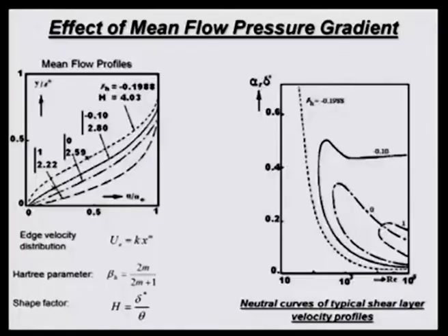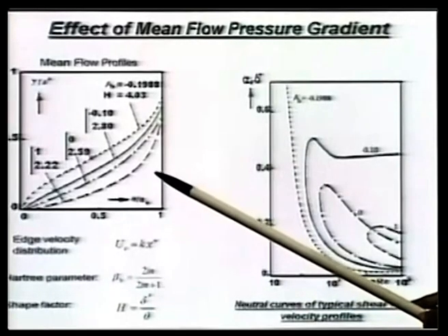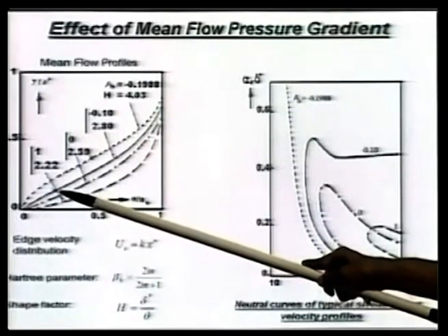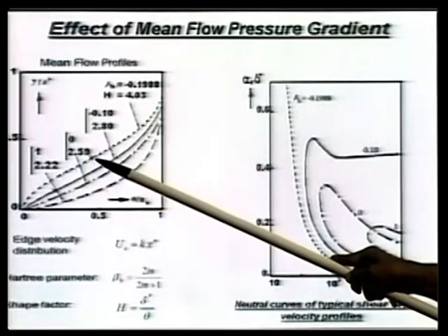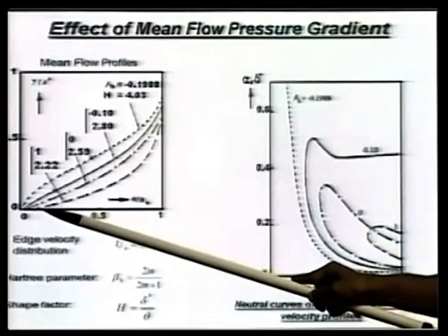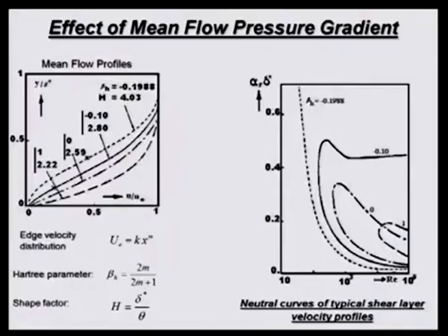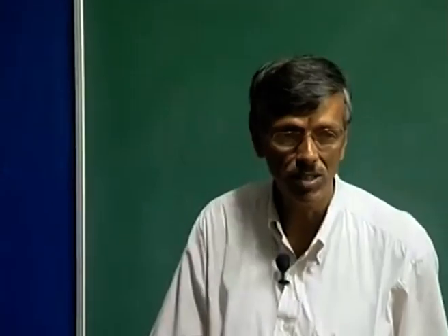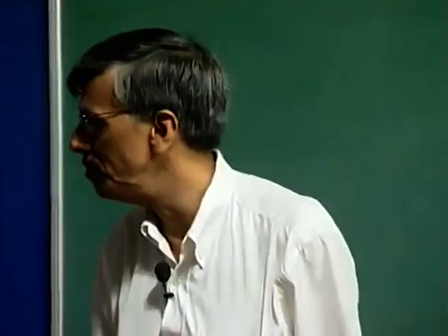And you notice that depending on the value of beta h, you would have a different location where you are going to have the inflection point marked by the crosses here. This is one here and the other one is there. I asked you the question last time also, you can remember that for the Blasius profile this point of inflection is actually on the surface, which is of no consequence because Rayleigh's theorem does not consider that flow to be unstable.